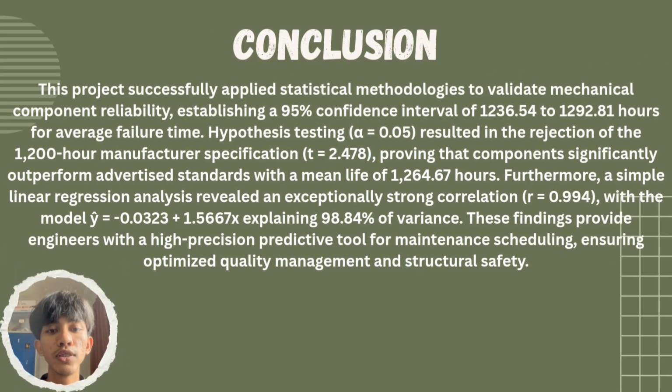So for the conclusion, this project successfully applies statistical methodologies to validate mechanical component reliability, establishing a 95% confidence interval of 1,236.54 to 1,292.81 hours for average failure times.